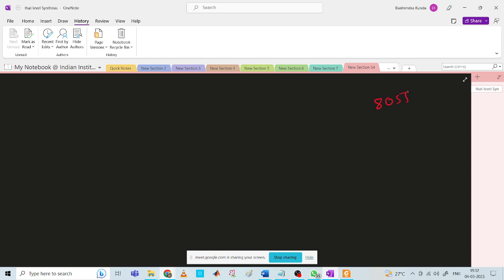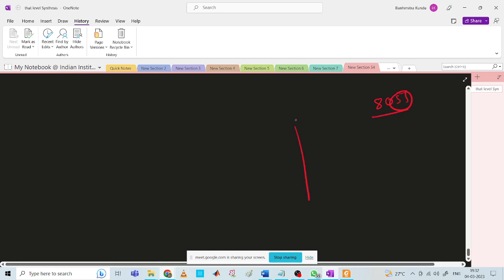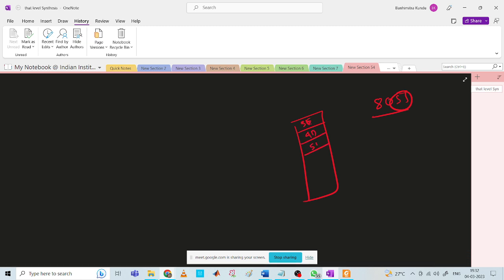8085, right? In 8085, you have many instructions in the memory. Let's say 3E, 4D, 5C, okay? But there has to be a code here. Whenever you fetch the data, this 3E has to be compared with some data, decoded to generate the next address signals, the control signals or the ALU signals, right?